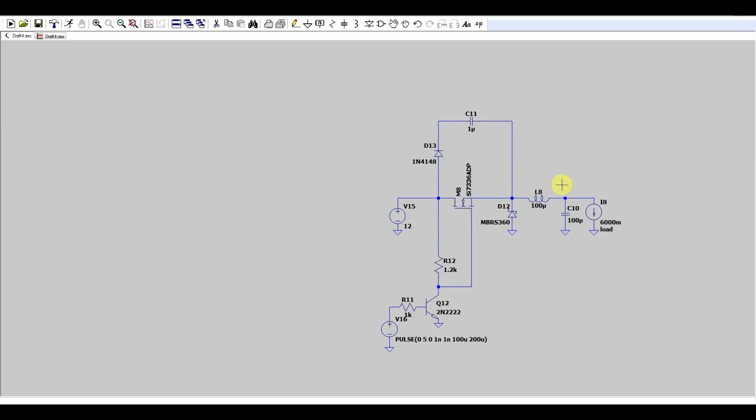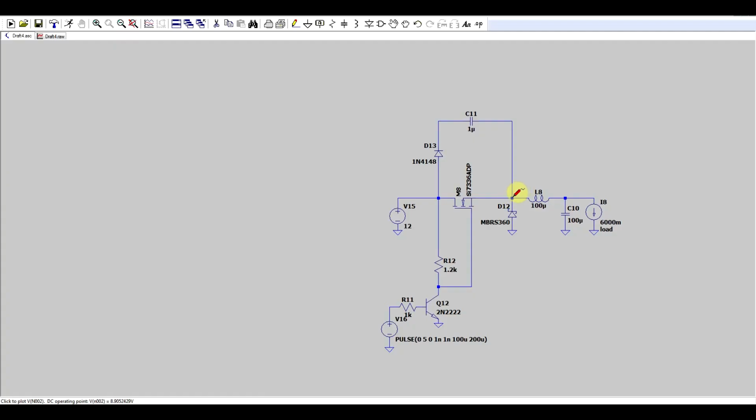And we can get a higher voltage with a circuit like this. So compared to the previous circuit, I added this capacitor and diode. And the logic behind this is that when the switching node is low, so at 0 volts or lower, then the diode will charge the capacitor. When the voltage in the switching node is high, then the voltage on the capacitor will be higher than that of the input voltage. This is also called a bootstrap capacitor.